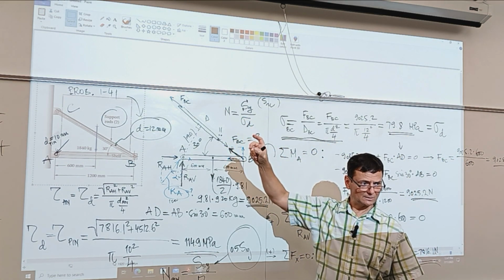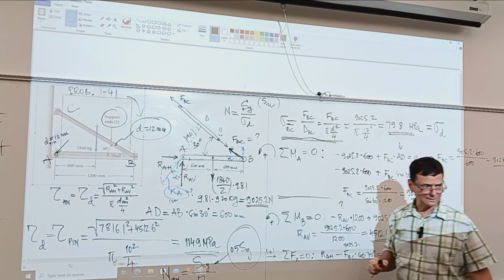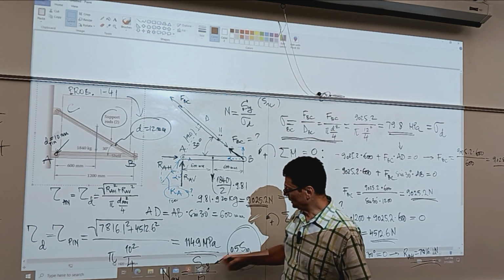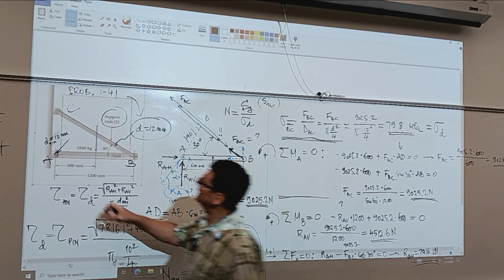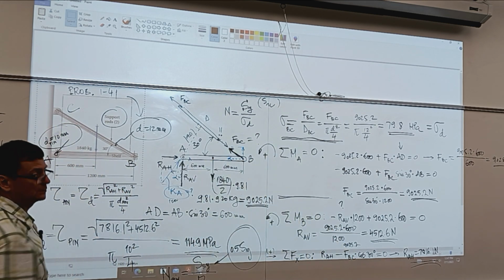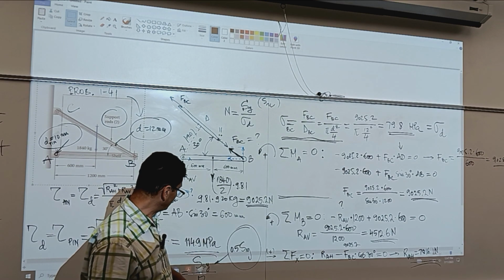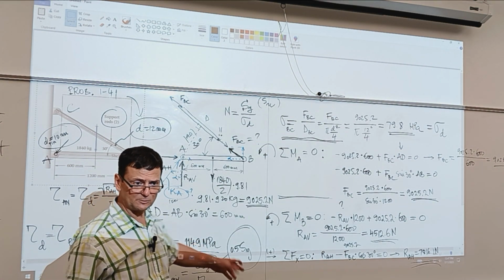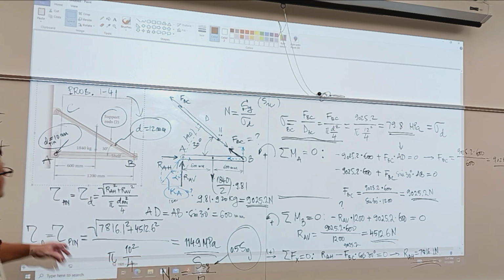That's pretty decent, good quality steel, and expensive. But to use the same material for the pin at this diameter, you'd need a very high strength steel, even more expensive, probably hard and difficult to work with.